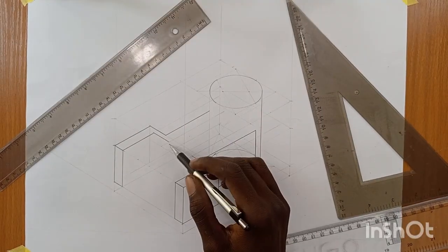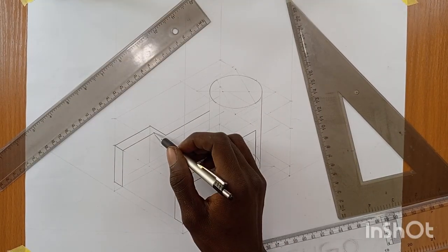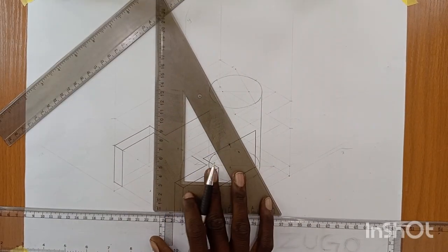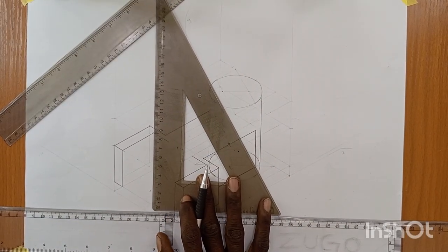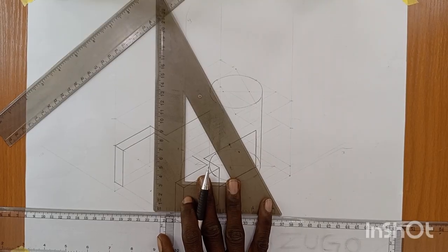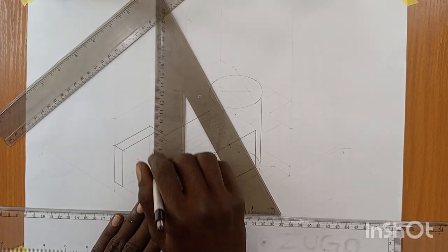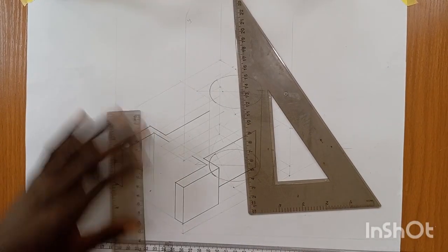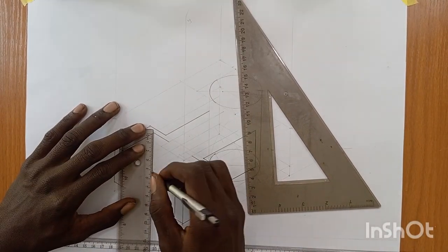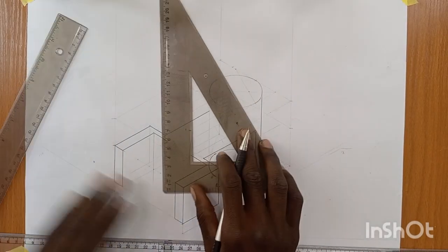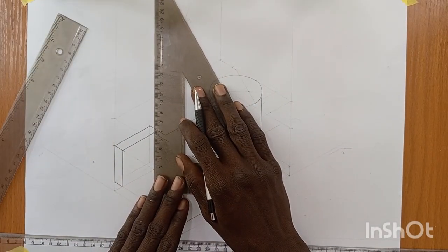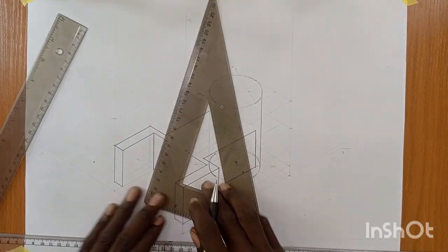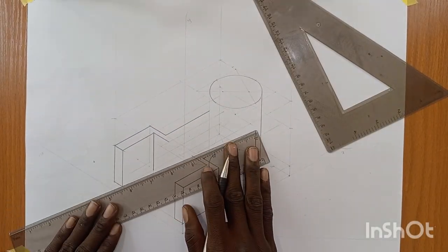Now this goes inward to it. This also is going to draw a line that comes downward. So just use your set square to draw it. Since this is given as 40, any line you draw downward is going to be 40. You can draw a construction and then you measure the length to be 40. And this, take it downward a bit, right? Then you measure the length of 40, then connect them. Here you measure length of 40. This is it. So we are going to darken this. Make this darker. And then you connect these points here.